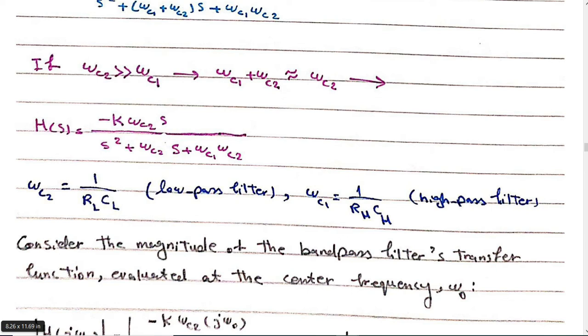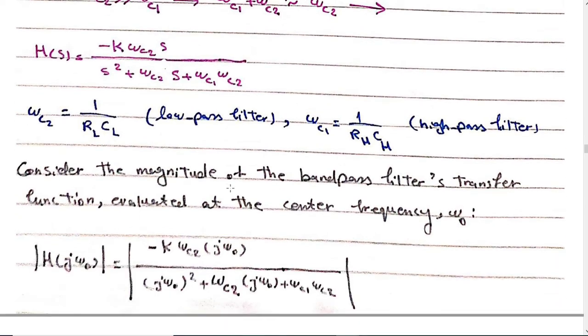Yes. Because we have individual circuits and we want the low pass filter to create our higher cutoff frequency, so we use the cutoff frequency of the low pass filter for omega C2. And what is the center frequency? Center frequency for band pass filter or for band reject filter. I explain.